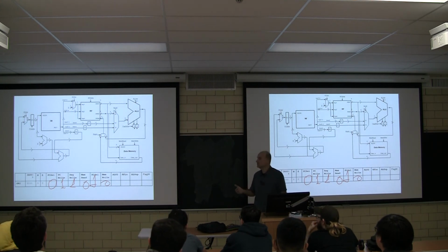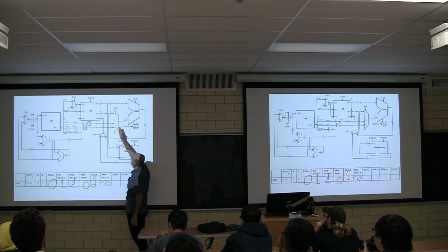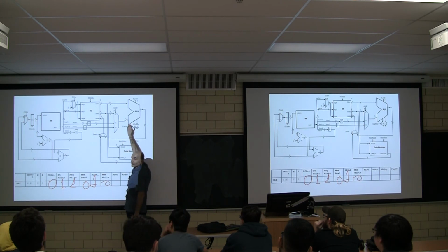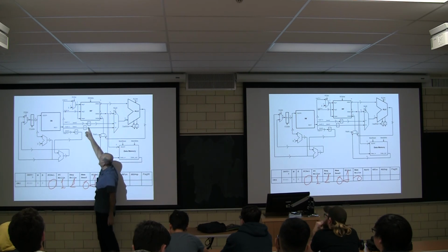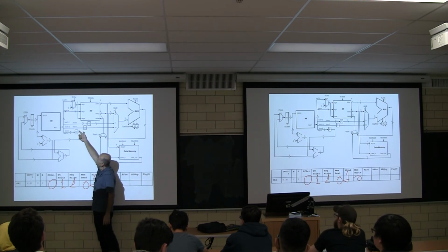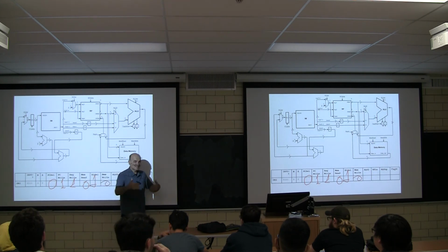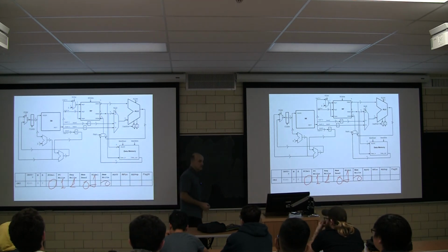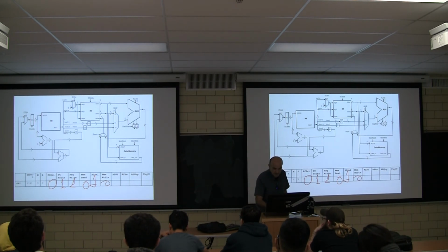Oh, ALU2 is the input, right? What should be the second... You're right. Absolutely. I'm lost again. What should be the input to the second port of the ALU? Should it be the register file? Should it be the immediate 5 extended to 8 bits, or the immediate 3 extended to 8 bits? This is ORI. The second operand is the immediate 5. For that reason, ALU2 should be 0 1.